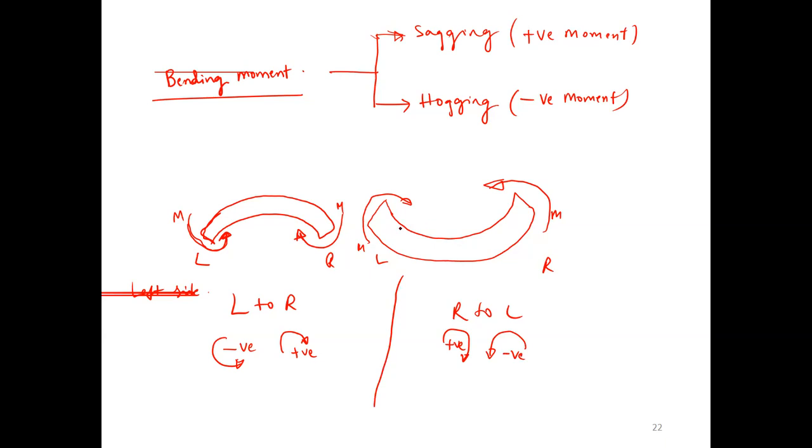If you are considering a section, left to right, left to right, clockwise positive, anti-clockwise negative. Right to left, clockwise is positive, anti-clockwise is negative. Clear? Concept is clear? Yes, sir.